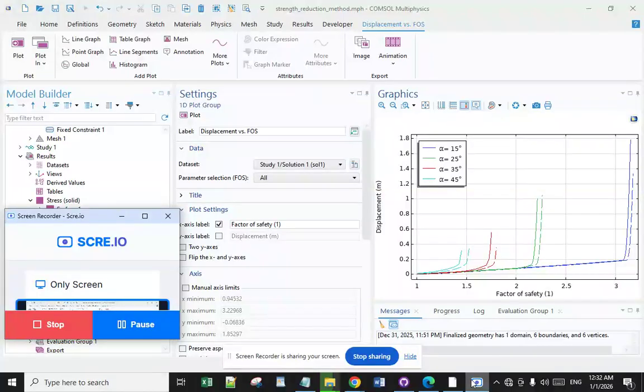Decreasing the material parameters results in a reduction of the shear strength of the soil, which eventually becomes unstable. This phenomenon produces a collapse of the slope for a certain combination of loads, material parameters, and boundary conditions. The ratio between the initial cohesion and the cohesion at failure gives the FOS. More details have been given in this simulation. The geometry, boundary conditions, loading conditions, and material parameters in this example have been given here in this configuration, in this simulation.